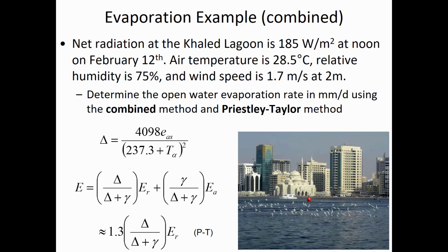I mean, the input value for energy balance was 6.55, and just because of the air temperature conditions we have, that's the primary factor that goes into the delta. Then Priestley-Taylor didn't give us much of a different answer than just the energy balance by itself.